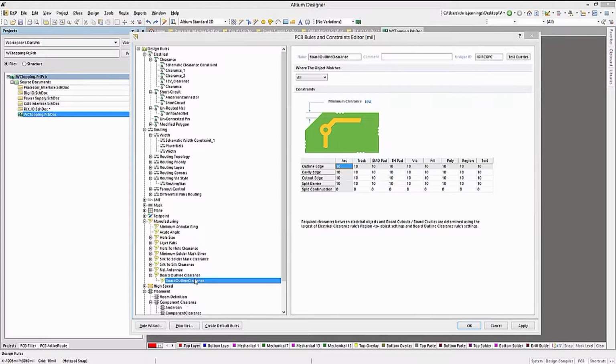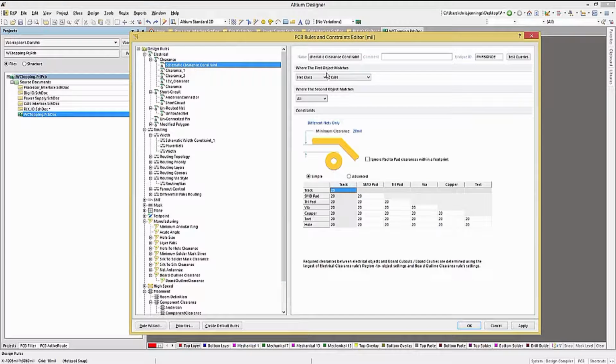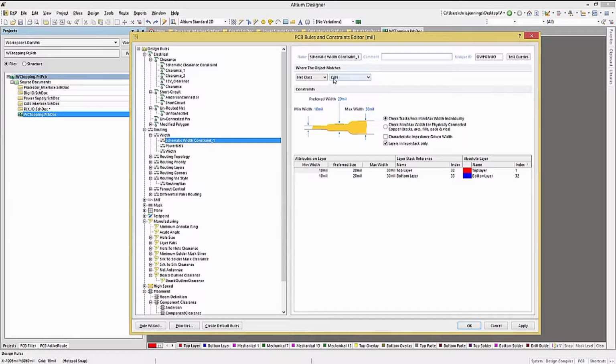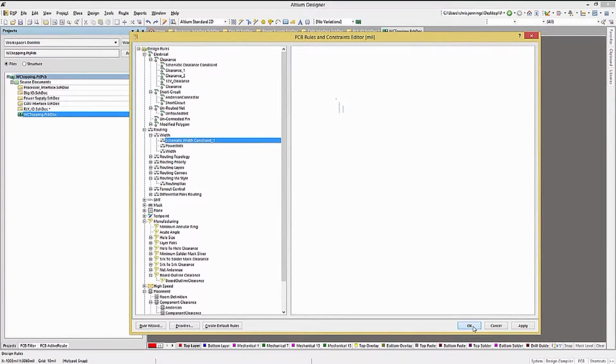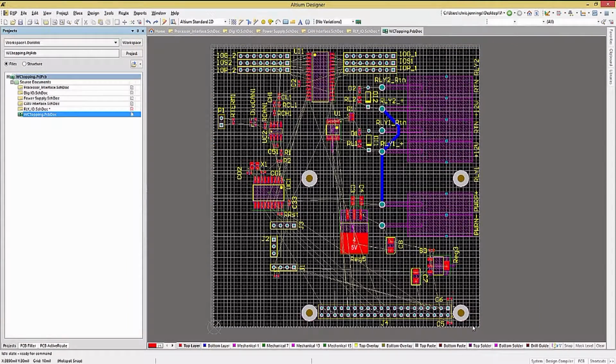While we are adding the net class directives, including a width rule makes sense. Here is the net class directive with the included rule. Now when, or if, we update the PCB from the schematics, there is no danger of accidentally deleting the net class. In combination with the PCB rules, the PCB preferences help drive both trace widths and via sizes.